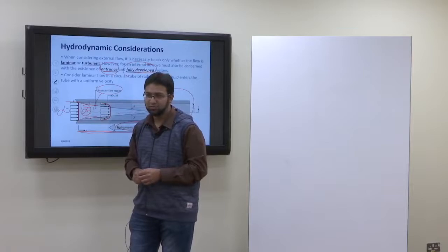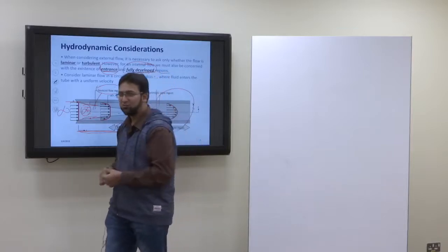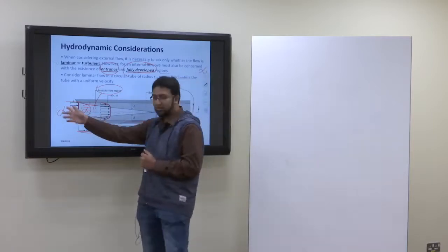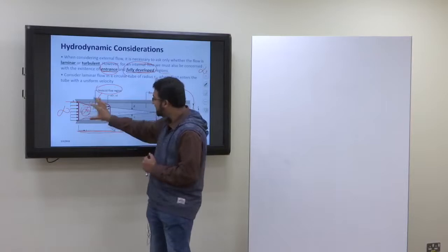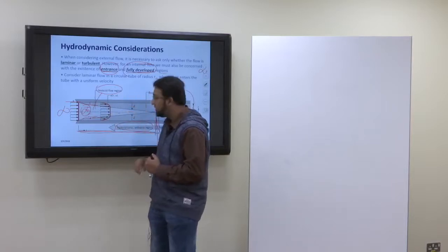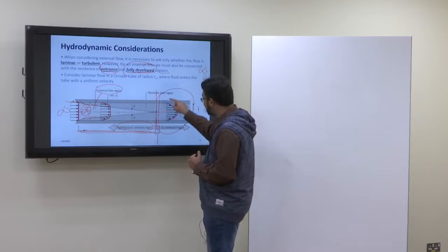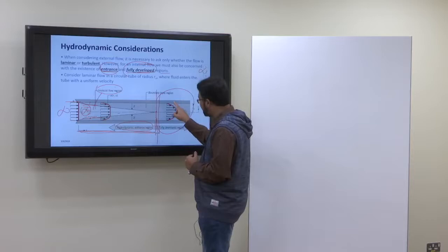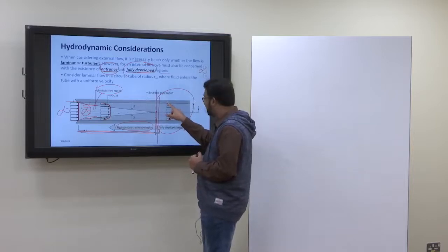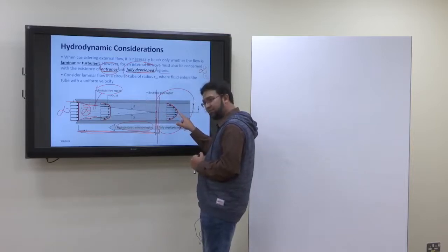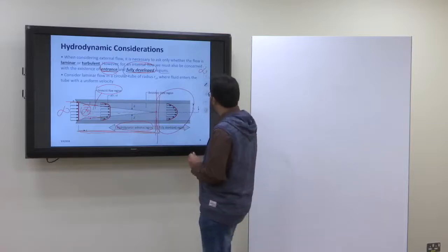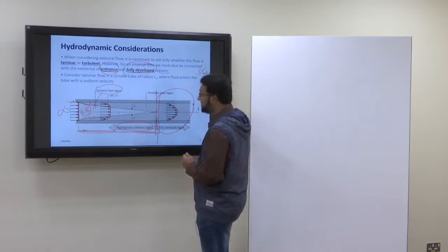So what are the kinds of velocities that we'll have? We'll have the free stream velocity, but that is only at the entry point or within the inviscid region. After the inviscid region finishes, you have a complete velocity distribution. Velocity starts from 0, becomes maximum at the center line, and then keeps on dropping, becoming 0 again at the other edge.